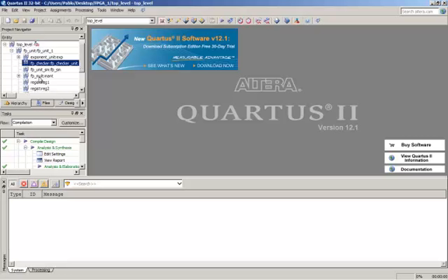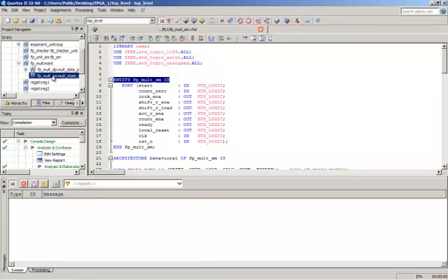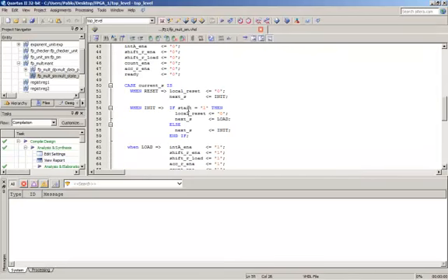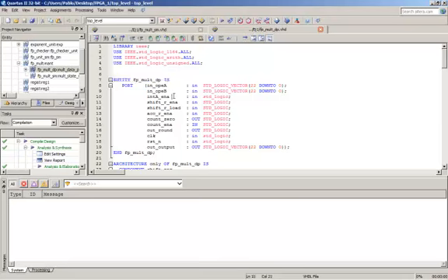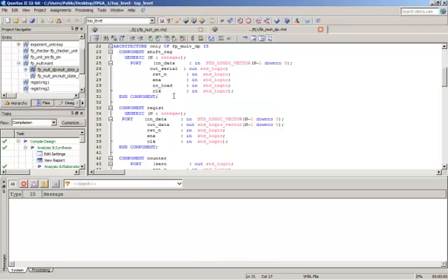Now we are going to see the floating point multiplication, which as I said was implemented using a sequential multiplication. This is just the multiplication of the mantissa. It is composed of one finite state machine and one data path. Inside the state machine we have the different states: reset, init, load, calc, done, and finish. And in the data path we have all the components that perform the movement of the data.